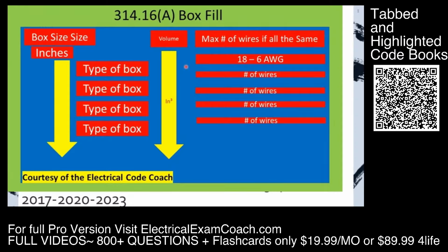And the reason it's cubic inches is because we have 3 different measurements. We have 4 by whatever the depth is. In this column, you're going to find the maximum that you're allowed to fill each box.